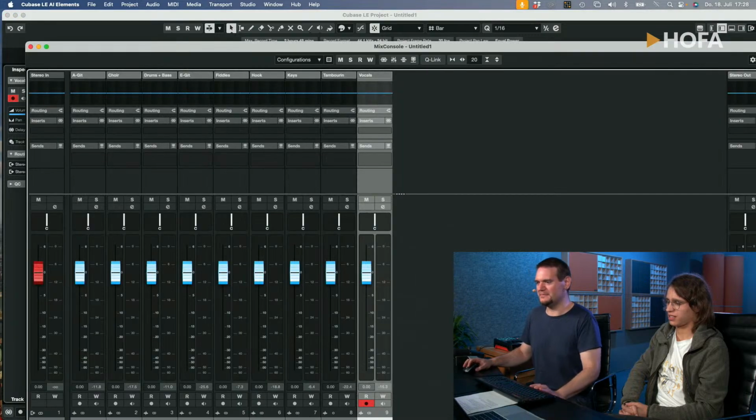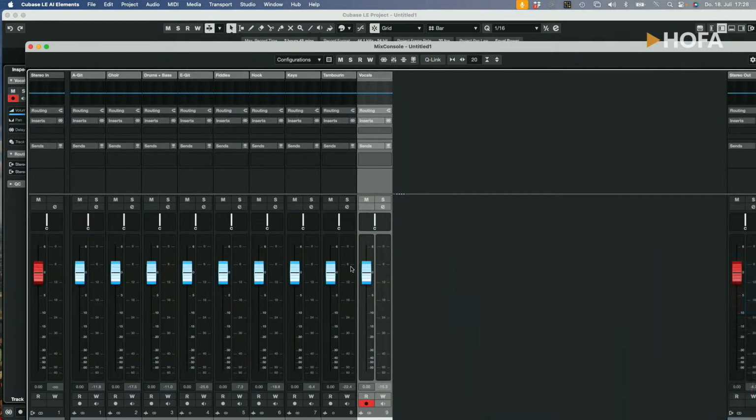So if we take the mixer's view, you can see that the levels are all set at 0. And these levels will add to each other, and finally the stereo out might go over the 0 dB, and there will be noticeable clipping, especially if you convert it down to maybe 16 or 24. It's not that bad in the 32-bit surroundings of your DAW, the internal processing, but when you bring it down, when it comes to the final mixdown, you might really have to face and deal with all of that. Okay, so I would say that we bring the levels down before we start any mixing.